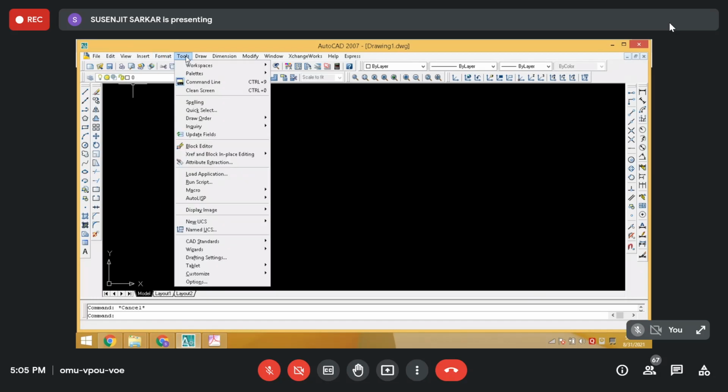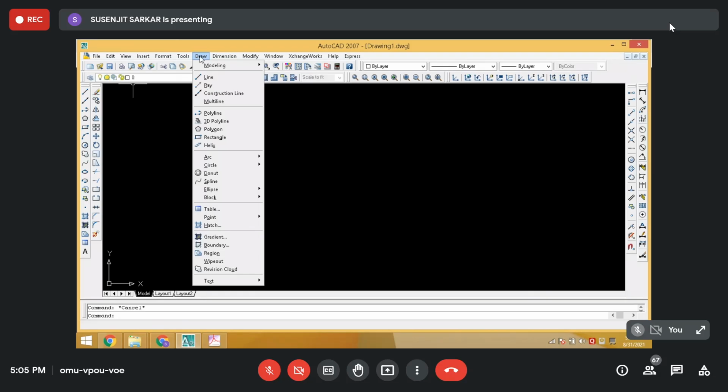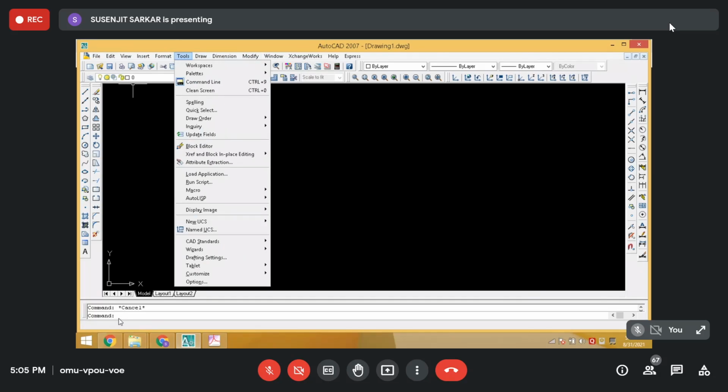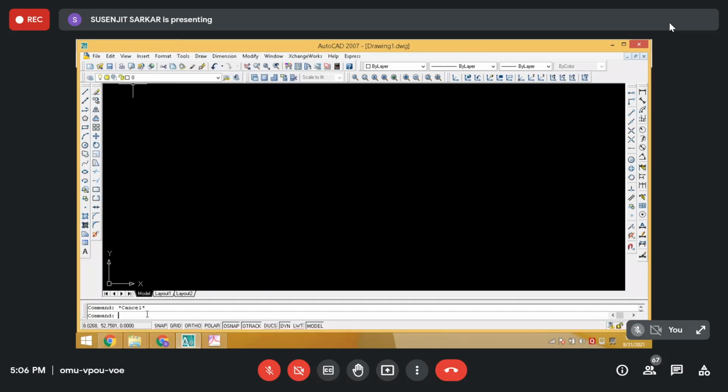Okay. Now, if I forgot, then what to do? There is a way. What is the way? Just write limit. Limits. If I write limit, it will give an error command. Press F1 for help. So the command is limit or limits.